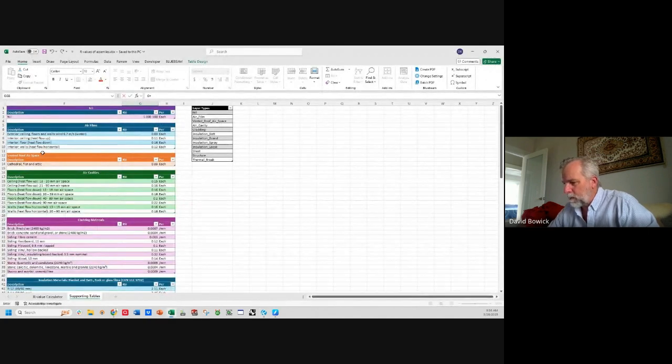So here's our spreadsheet, categorized everything here. These are a list of categories and these are a list of tables. So we're going to come here and we're going to look at air films, interior walls. Here is our RSI value, and the quantity is each and the per each. So the interior air film has an R value of 0.12.